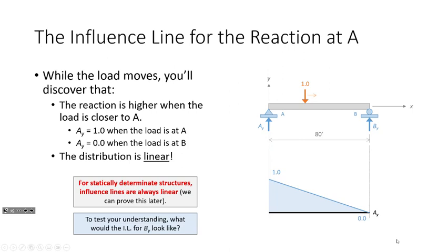No. Okay? If you are drawing a curved influence line for a statically determinate structure, you are doing something wrong. We can prove this later with the Mueller-Breslau principle. But you'll see what I mean here in a second. Now, let's make sure that we're clear.